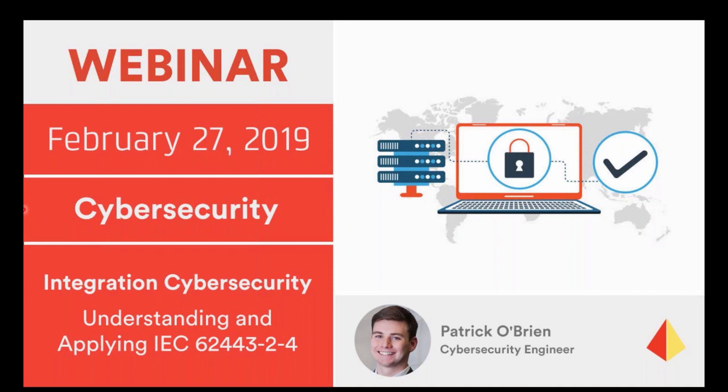And the last point is that specifically what the asset owner needs to see certified will vary from asset owner to asset owner. They are pushing what needs to be certified and asking their service providers to demonstrate certification to the 62443 standard, as well as requiring that specific components are at a defined security level. That will be a market demand that's also driving certification.